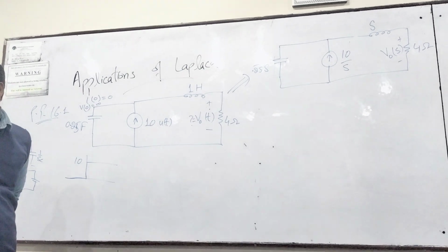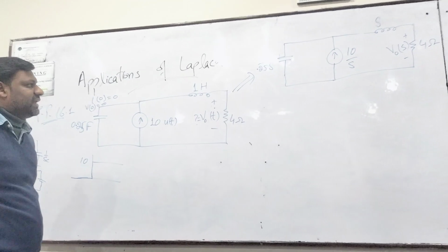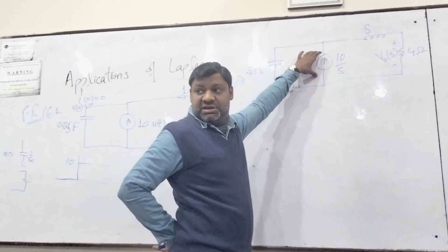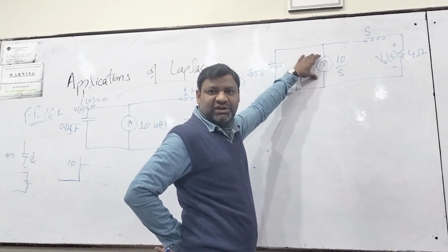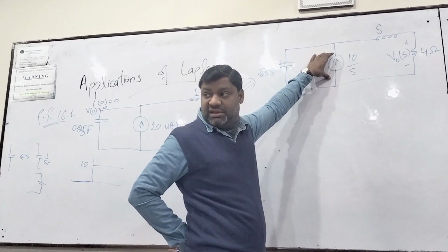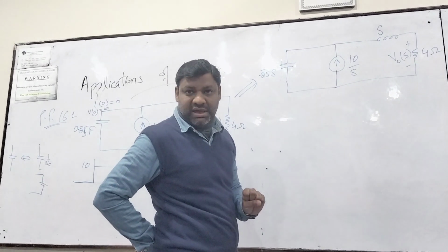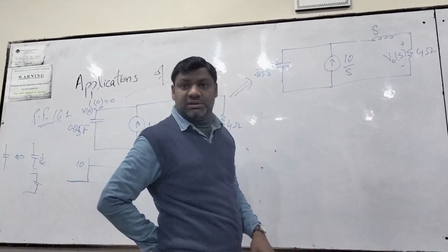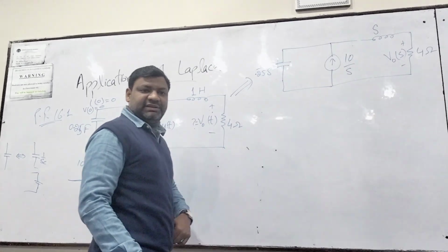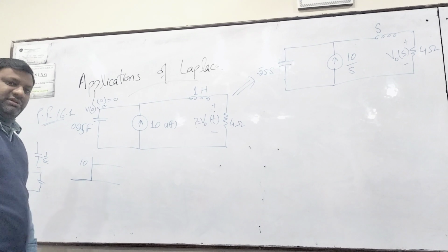Okay, that's a good way as well. As we have this impedance in parallel with this current source, we could use source transformation and transform this current source into a voltage source in series with this capacitor. Then all of this will be in series and you will go. Any other thing? Source transformation, any other? No, that option is gone.